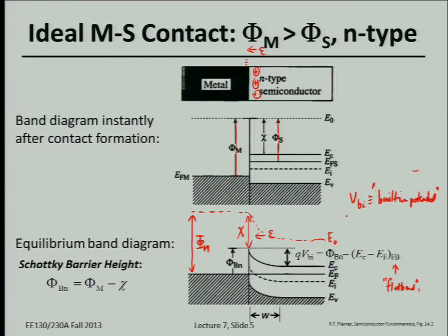Okay, so that's basically a Schottky barrier, Schottky contact. Just qualitatively, before we go, next time we'll derive the current equation. But basically, because of this large barrier to electrons diffusing into the semiconductor, it is very difficult to get electrons to move to the right. So you won't get much current flowing. Electrons moving to the right is negative current. So if you apply negative bias, you won't be able to get much negative current to flow.